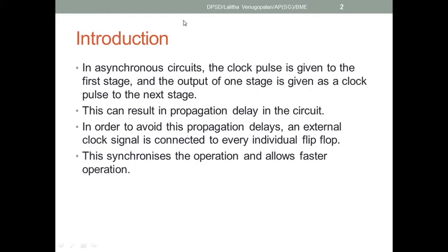Asynchronous circuits use just one external clock pulse given to one particular stage, and the output of that stage is fed as a clock for the next subsequent stages. So there is definitely a propagation delay, because the first circuit has to complete its operation before the next stage can commence its operation.